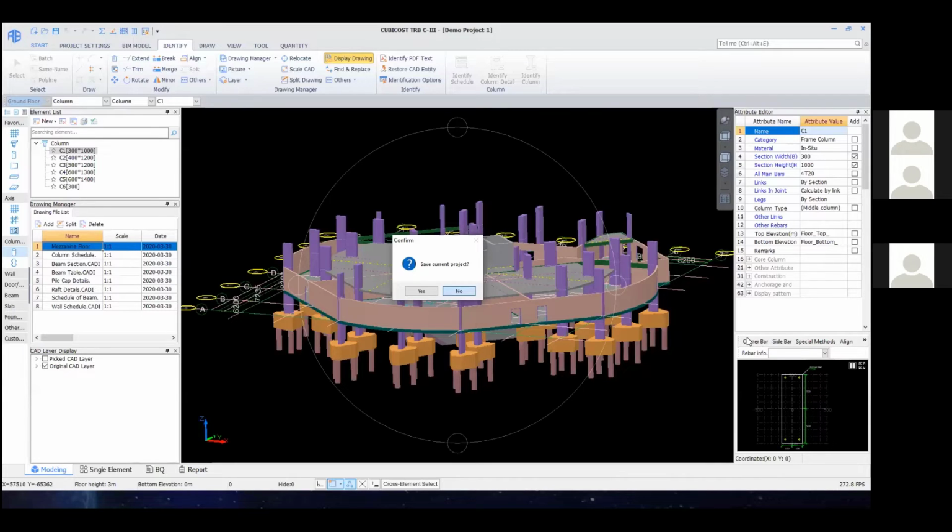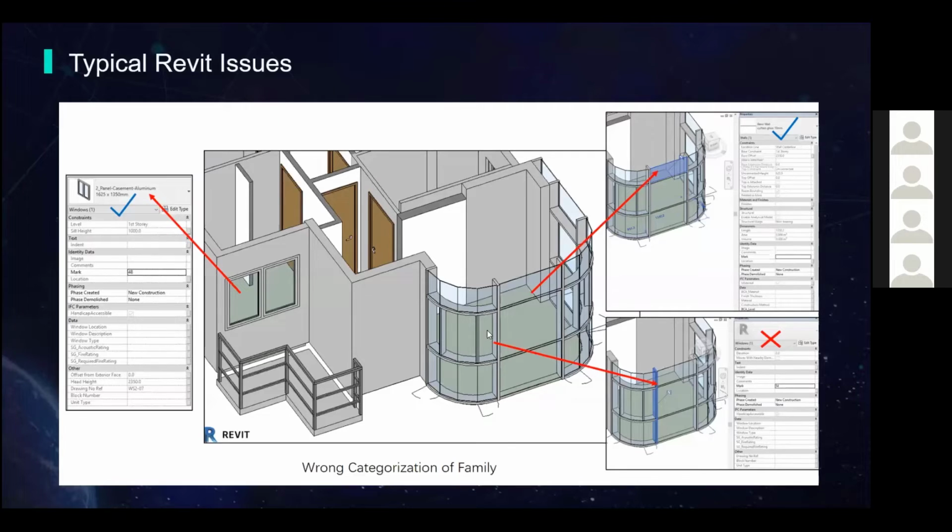Similarly, you should not give this another name, or call this particular part an opening or window or something else. That should not be the case. You have to call it a complete wall going throughout, and then you can say there is another window. If you say there is no wall and there is a window, you may end up with less quantity of wall. So it's a little bit of principle, but it works well when you follow those principles inside your Revit modeling.